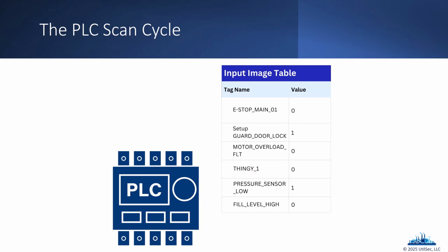Remember, when we connect to that controller over an OT protocol like Modbus, we're just seeing the zeros and ones for the coils or the higher values for the registers. We don't actually see the tag names. We have to find the tag names in other systems, whether on the engineering workstation or on a data historian. But just keep it in the back of your mind that those zeros and ones do have associated tags. You just don't see them. But if you did, I think it would make life much easier on you as a pen tester or as an attacker trying to reverse engineer the environment to determine what's going on.